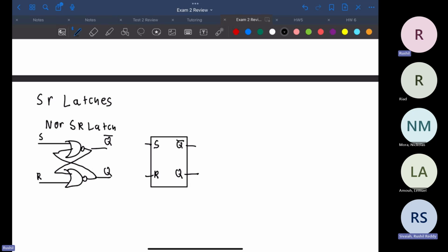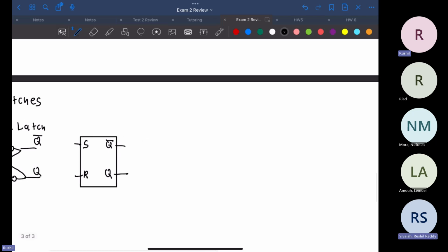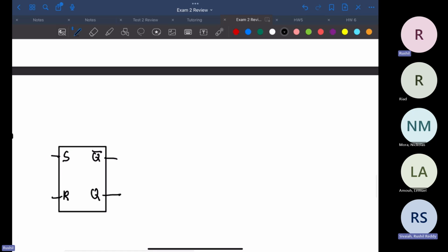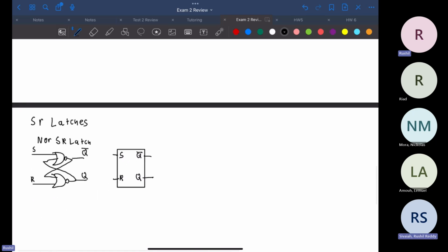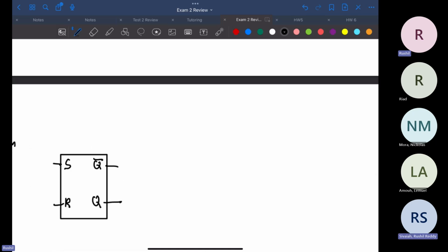So we're gonna say that there's 3 inputs because you have your S, your R, and then your feedback from Q. Technically, because it's going into the gate. It'll make your life easier. Actually, not really, but I prefer it, so we're gonna do it that way. We're just gonna assume that the Q naught is inside here, because instead of just writing Q naught, it's already presented in the truth table, right? Because if you have Q, you know what Q naught is. But yes, technically that's correct.